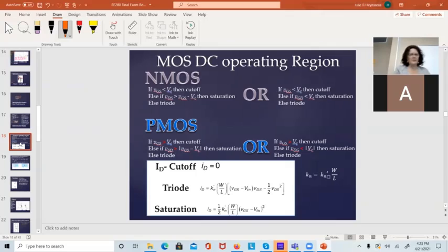Okay, so there's 2 MOSFET problems on the exam. You got this on exam 2. If it's NMOS, can you look at the picture of the device and tell me which is the drain and which is the gate and which is the source? Can you calculate VDS, VGS, and then later on ID? Use the little algorithms, either one of these, to figure out what operating region it's in, and then calculate the current. So that's the idea. You'll get trickier versions of this when we get to 380, because I'll add in things like the channel length modulation and the body effect. It's not so bad. PMOS, same thing. So that's a good thing to go back and review.